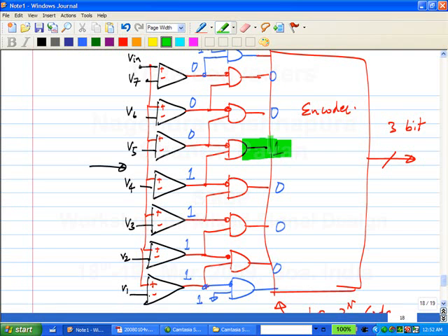So the flash A to D conversion process, therefore, is basically, if you have n bits, this is what you do. For a 3-bit example, I can draw it on the board. There are 7 comparators. If you have a 6-bit A to D converter, how many will be there? 2 to the power 6 minus 1, which is how much? 63 comparators, right? If you want to build a 10-bit flash converter, how many will be there? 1023, right? So if you want to build a 16-bit comparator, how many will be there?